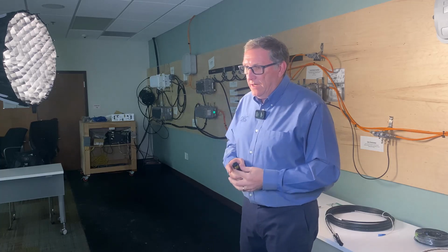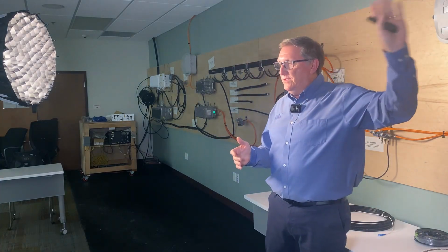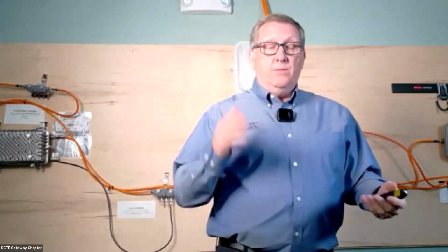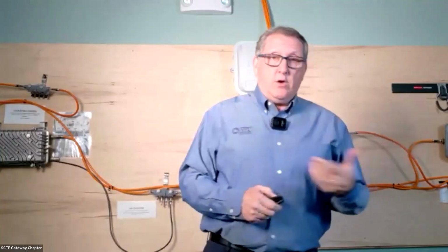Modern OTDRs are designed to shoot hundreds of thousands of kilometers. They can be really powerful, especially when they're tunable. They can shoot through muxes. Most OTDRs can't shoot through a mux. It stops because it's working on a wavelength that doesn't go out all the ports. So the scenario we're talking about is somebody went out with a DWDM tunable OTDR in an urban environment.